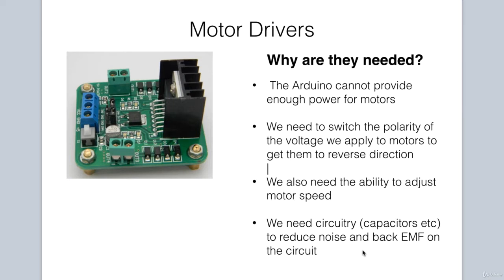Finally, when motors constantly change direction and speed, because electromagnetic fields are being generated and torn down, they create a back EMF on our circuit. As the magnetic fields are dying, they interact with wires and generate small, tiny currents that go back into our circuit. If you connect your motors directly to the Arduino, this can create brownouts, and the current could mess with the operation of the Arduino board and even cause it to reset.